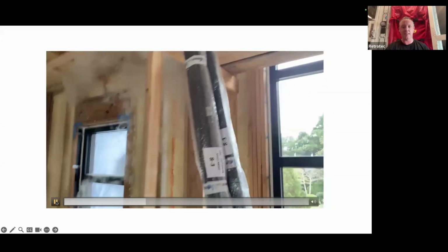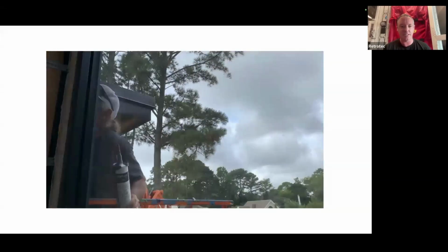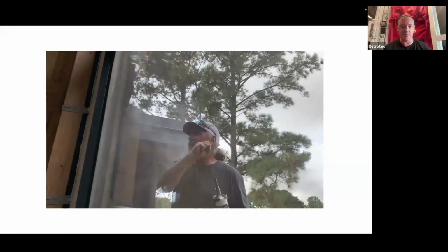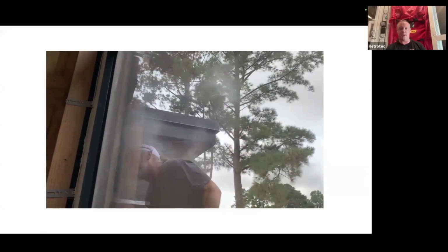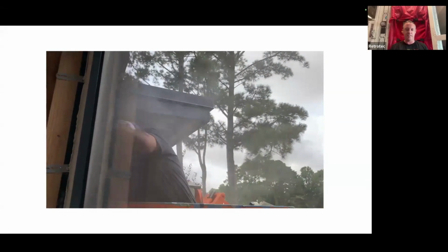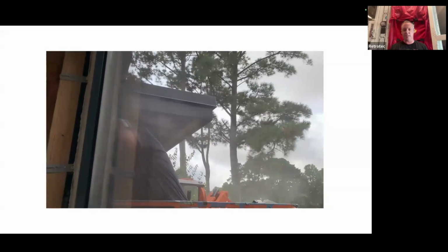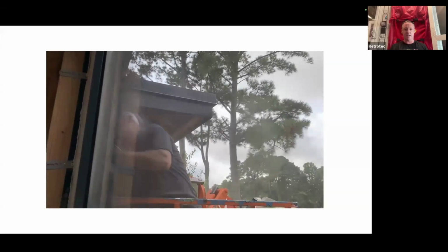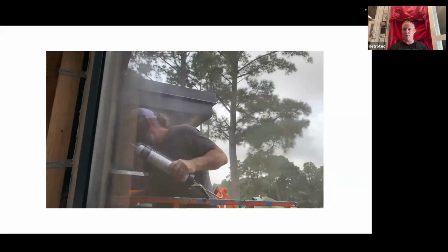And what we learned from doing this is that they missed a lot of those penetrations where that gutter went into the envelope. So here you can see that fog getting pushed right out where that gutter goes into the house. So now he can see where it's coming from. He can trace it down, get up under there and actively seal it as we're finding it.